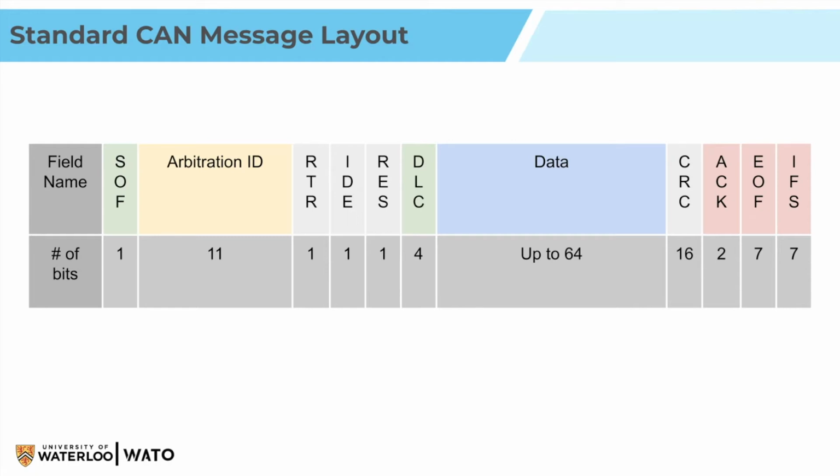And finally, the last one that is relevant is the ACK, or acknowledge bits. These are set initially to 0, and then on the receiving side, it's going to set these bits to 1 in order to acknowledge that it has received this message properly. If the acknowledge bits are not 0, then you probably would not have to take in this message and you may just ignore it.